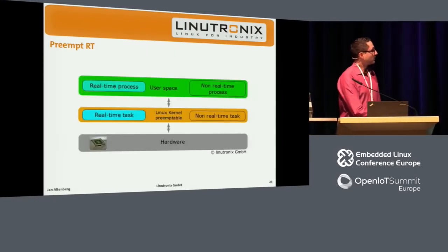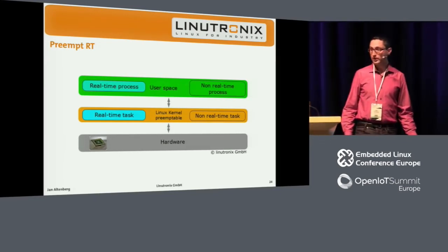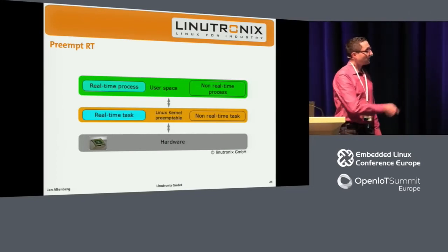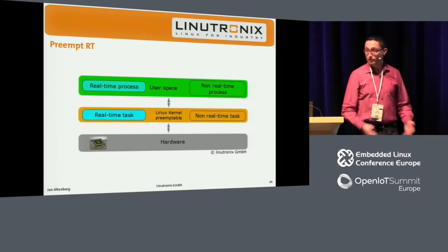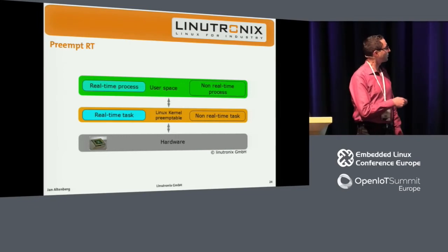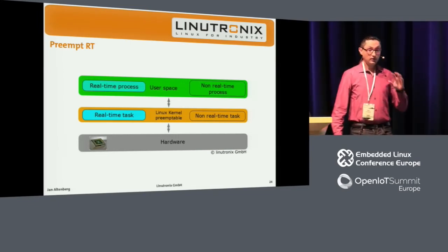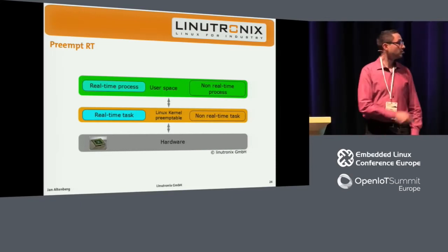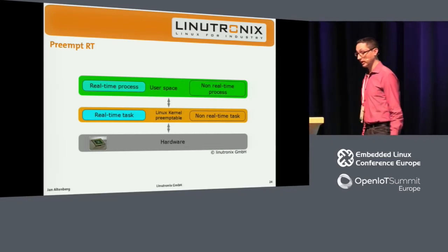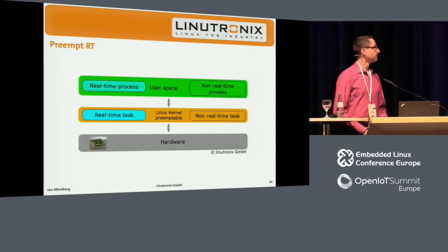So, well, this is just last but not least a quick overview of how the real-time preemption patch, this single kernel approach, is working. So basically, well, you can't see any difference to standard Linux. It's just standard Linux, right? Just with a new preemption model. So there's nothing special about it. So if you do a kernel driver, it's just a Linux driver. If you do a real-time application, it's just a Linux application. So you don't need any special libraries or special API. You just do a Linux driver or POSIX application. That's it.